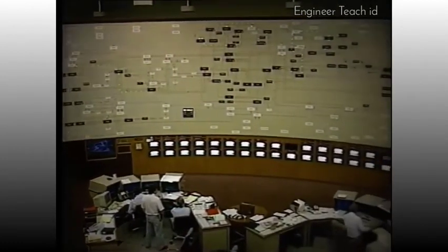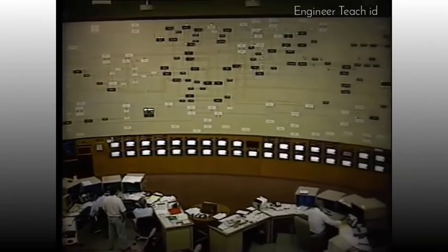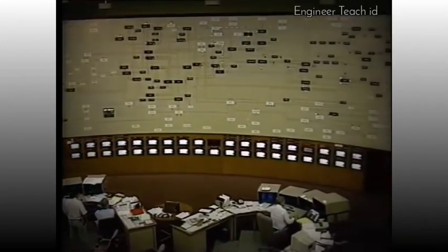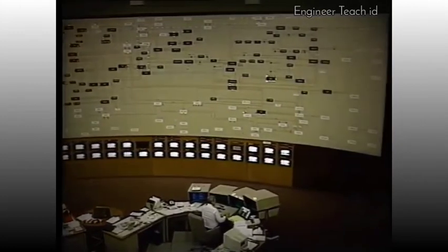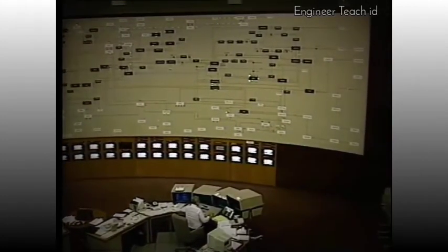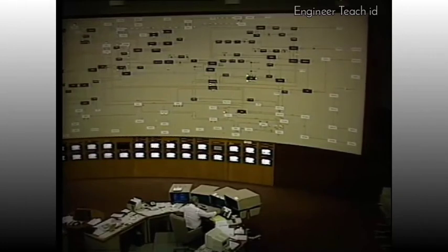However, he is assisted by computer programming and by automatic devices such as the turbine governor and the dispatcher's automatic generation control system, known as AGC. We mention all this as background so that you can appreciate the dispatcher's urgent appeal to you on occasion for either a rapid increase or decrease of unit output.